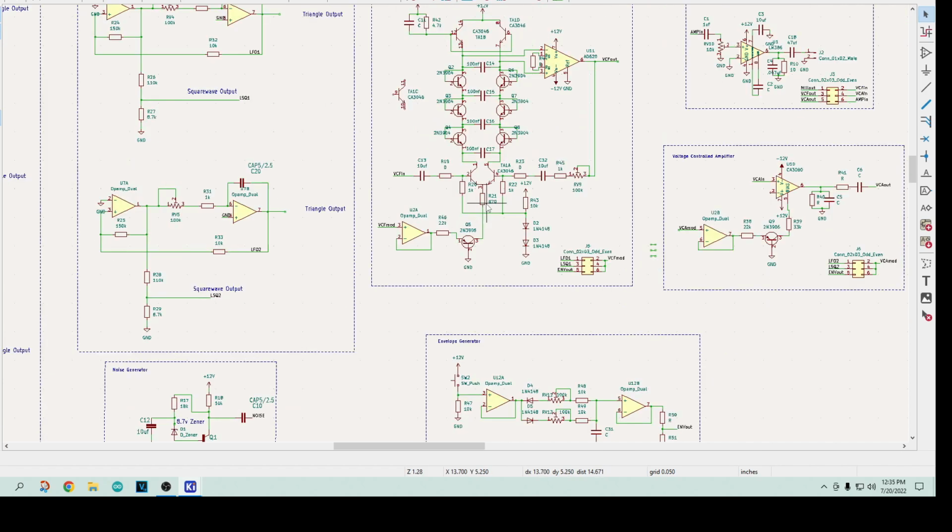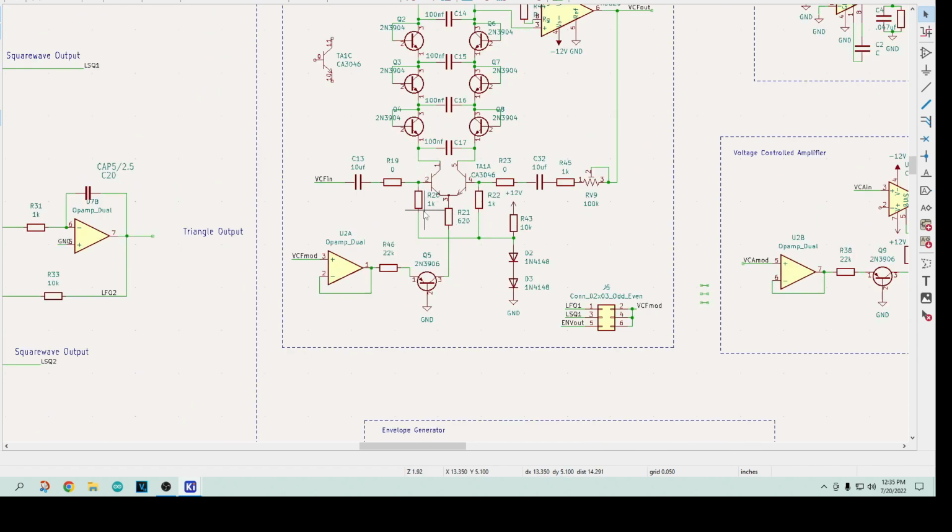The other thing I did without breadboarding is these 1K resistors on the bases of the transistors here. I originally had them ground referenced, and then I had the current going to a negative rail, and I've gone ahead and biased them up a little bit. This is the same thing as what the Moog filter is doing. Yeah, so I'm hoping that's okay. I can always go back to changing things a bit. But anyway, let's see what else I did here.